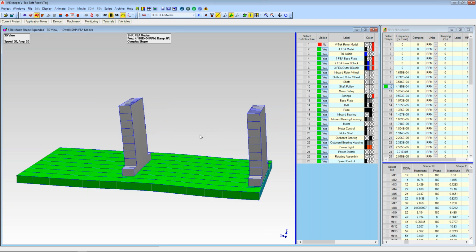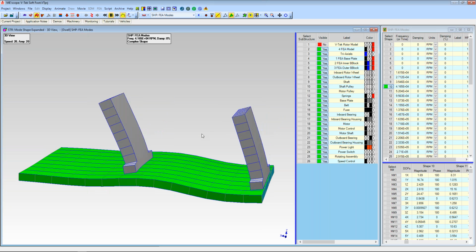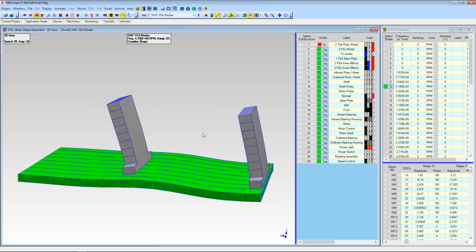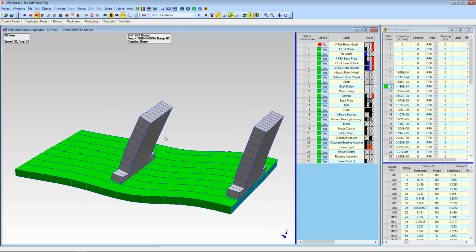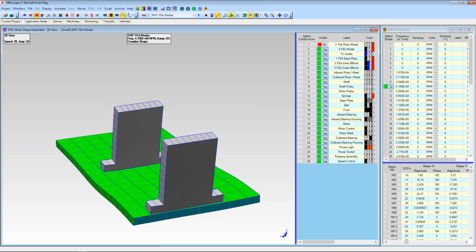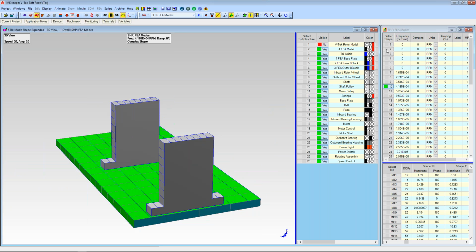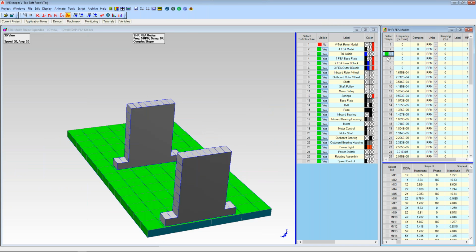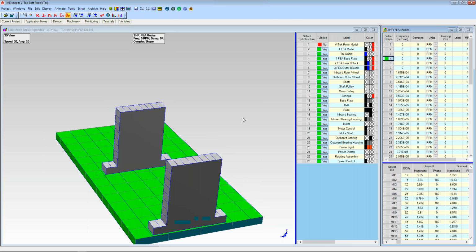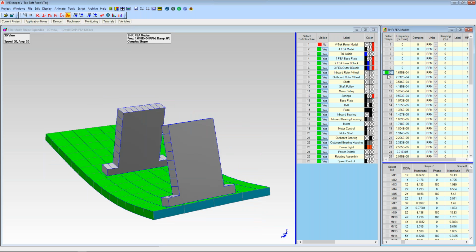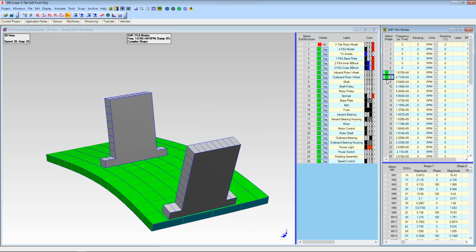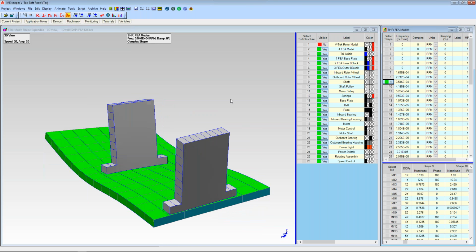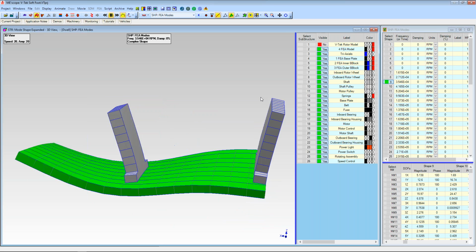It's like using too many polynomial terms to curve fit your FRF data. You don't want to use too many modes to curve fit the ODS data. But we did want to include the rigid body because the machine is primarily bouncing around as a rigid body in space on its rubber mounts, but there is a little bit of flex in it also. So let me just go back and we'll look at the different ODS data.